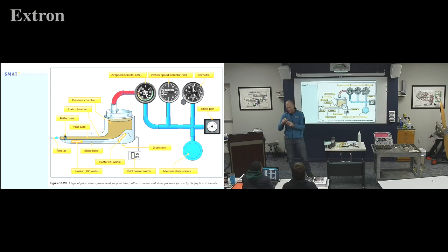This particular one, it's actually right here. If it was mounted on the aircraft, it's kind of at the low point. On the Beach jet, this thing's mounted on an angle like this, and the holes are, I think, one down here and two back here. Part of it is if moisture got in there, we don't want it to sit and freeze when the aircraft's not on. So they'll put one at the low point, but they'll also put some where ram air is going to push it out. So be aware of that on pitot tubes. I'll pass this one around. There's going to be drain holes on them somewhere, so when you're doing the test we talk about today, you're going to want to find the pitot tube drain holes and cover them up.